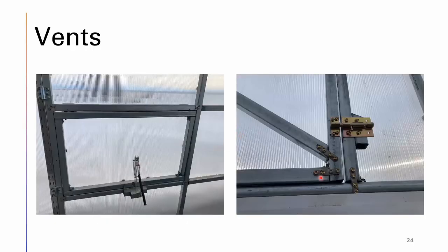The other thing I wanted to do is mention vents. You absolutely have to have your vents. There's an aspect ratio that's recommended. It's 2-to-1. The kits I sold last year were 8 meter by 16 meter. It was intentionally done that way because then you only need gable vents. So if your length is twice the width or less, you can just get away with gable vents rather than having vents all over your roof. At least that's my observation, and that seems to be written in the literature.